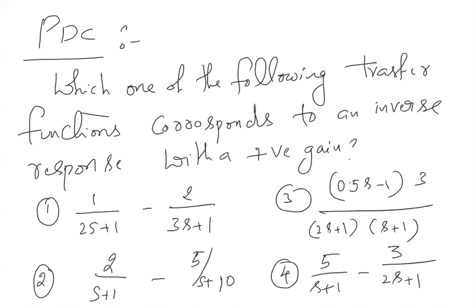How do you find inverse response? All these things you have to find the response for a step input. Take these transfer functions, let's say y by x. Take x equal to 1 by s. Find the inverse Laplace transform, then you will find the response. Then you have to find the slopes.